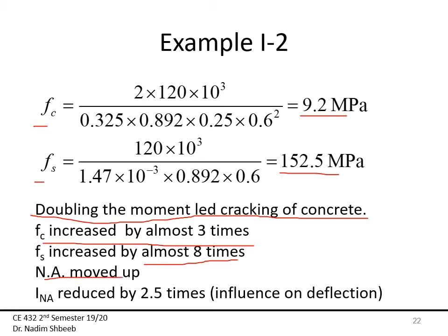The neutral axis moved up, and the second moment of area was reduced to 1/2, which means it will have some influence on deflection, and by that I mean the deflection will increase. Obviously, if you increase the load, the deflection would increase.